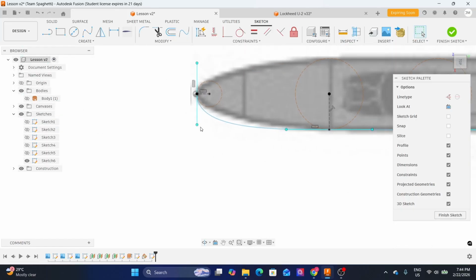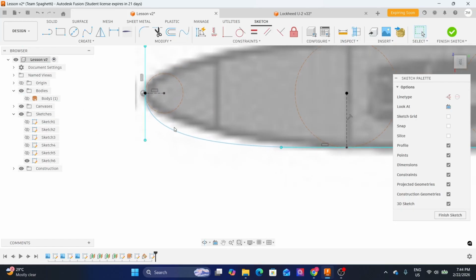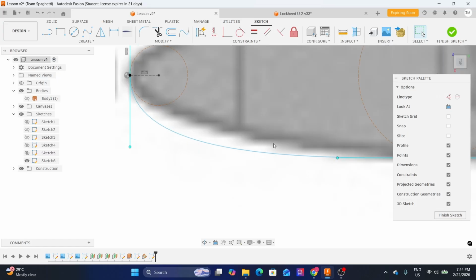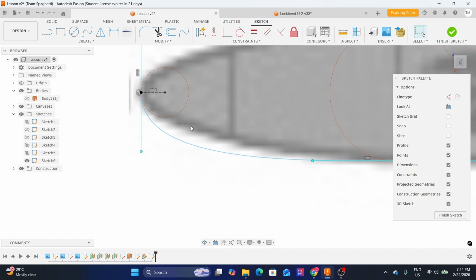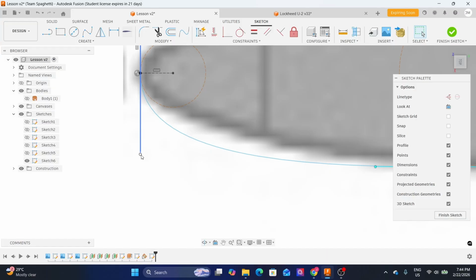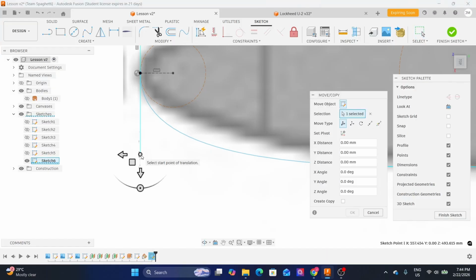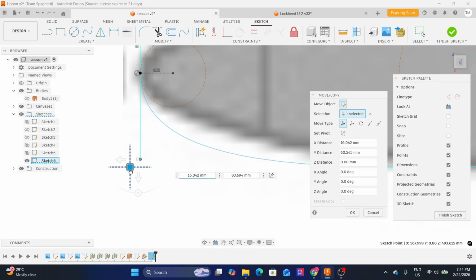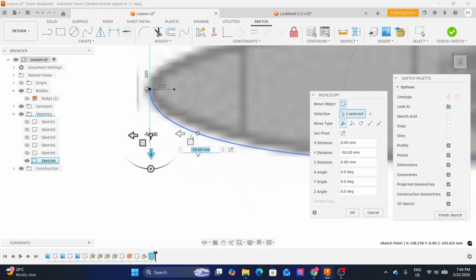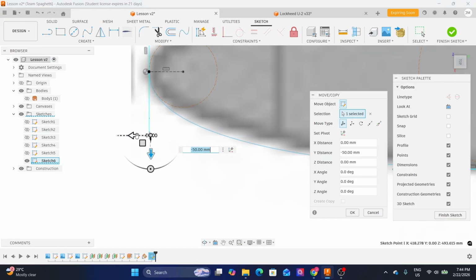And we'll just need to adjust this so we could get this outline of the nose part of the aircraft here. So again, from the point of this tangent handle, I'll select this point. I'll press M on my keyboard. You could select either this or this to adjust the fit point spline, but this doesn't matter since it is vertically constrained, so this wouldn't matter anymore.